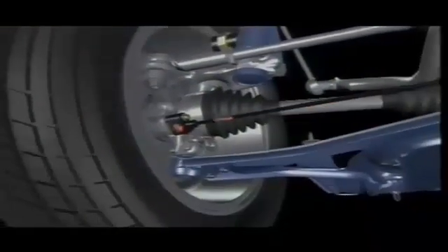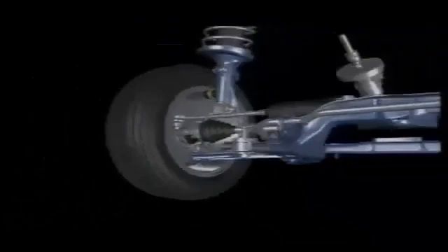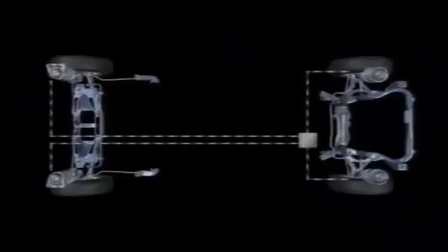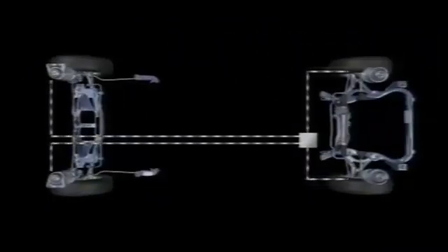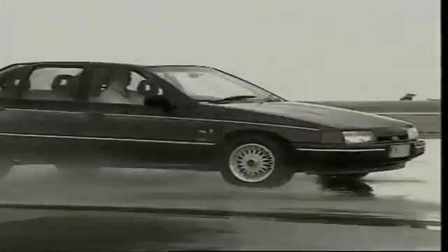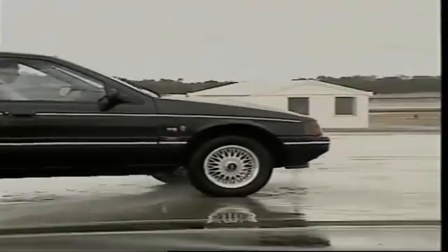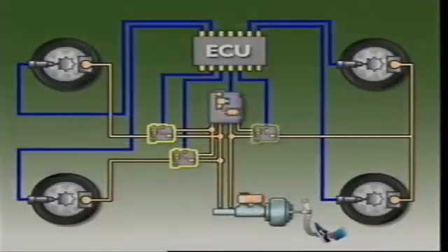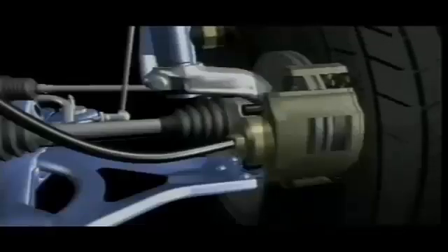Another input is from the wheel speed sensors. These signals are used to control the hydraulic control unit and anticipate wheel lock. If a wheel starts to lock, the electronic control unit operates the solenoid valves to reduce hydraulic pressure appropriately.